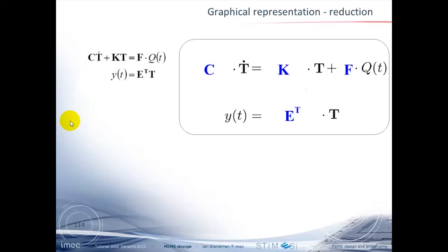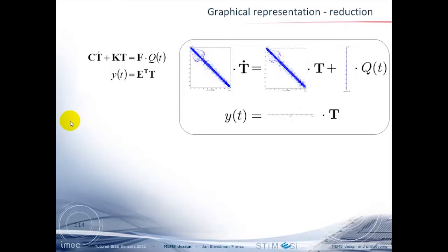Here is again this state space representation, and you see the same matrix appearing. If you look at a typical thermal simulation, these are typically sparse matrices. It's logical. If I have a huge structure and I have a mesh here, the temperature of an element is of course only affected by the elements in the neighborhood and not by the elements over there. So that's why for thermal problems you typically have a lot of zeros. It's not the case for all physics. In electromagnetics, something which happens there can directly influence all my elements. So you have to be careful about that.